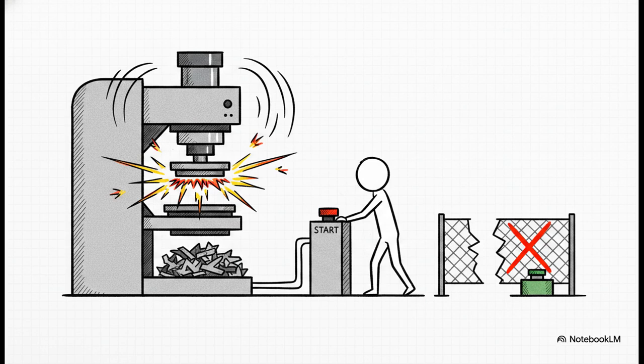There is a massive diagnostic trap waiting for you if you get sloppy with this code. If you fail to properly group those OR branches into subcircuits, like say you just forget to type that AND block instruction in your STL, you're going to end up with one massive continuous OR chain. And what happens then? Well, you get an unintended bypass of that second safety condition. An operator could literally just press IN1 and boom, the machine turns on immediately, completely ignoring the IN3 and IN4 safety requirement. Out there in industrial automation, that kind of mistake costs fingers or much, much worse. So please, structure your logic.